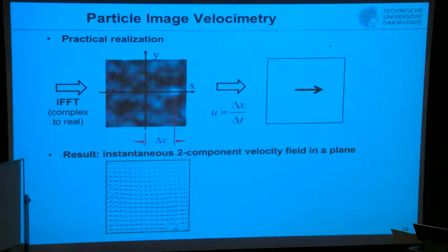So count the number of particles in your probe volume. It could be that you're losing many of the particles between the two shots, so you should make the delta T smaller or the light sheet thicker. These are, as I said, different things that need to be controlled by the experimentalist, and there is not one best way, because you have different possibilities to overcome a bad image.